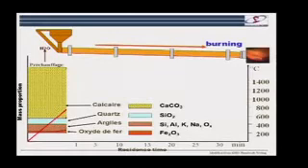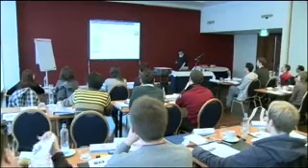So what we're going to look at here are the basic changes that occur in the cement kiln, and you don't need to worry too much about the steps on the way. What's important is to realize that this is what we start off with, our limestone, quartz, clay, etc., and what we're going to end up with here is the final clinker. And as we move along the kiln, as I said, the temperature is going to increase. This red line shows the temperature. And this is roughly the time going along there.